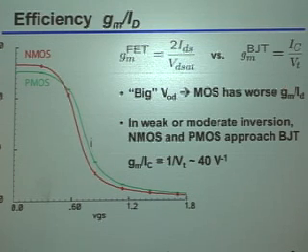Whereas with CMOS, the best we can do is, if we bring it all the way down to the subthreshold region, we'll get close to that, 40 inverse volts of efficiency, but because of that capacitive coupling or the capacitive divider, you don't get the full 40 inverse volts. Instead, you get something like 25, 26, something in that ballpark. Okay? Does this make sense to people, or?